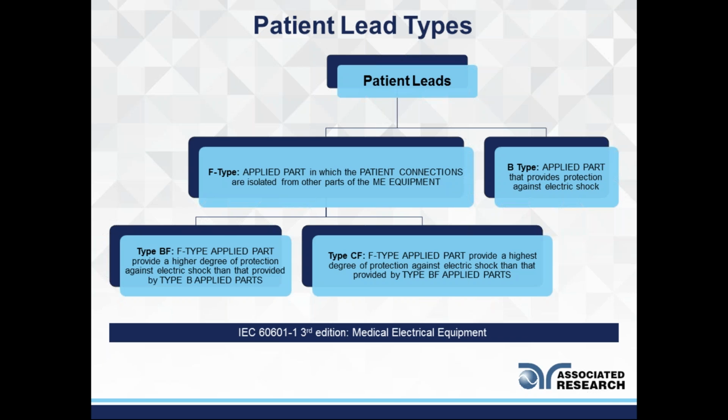Now F-type is like a floating B-type. So you can have that F stand for floating. It's an applied part in which the patient connections are isolated from other parts of the medical electrical equipment. So that's what ME stands for.